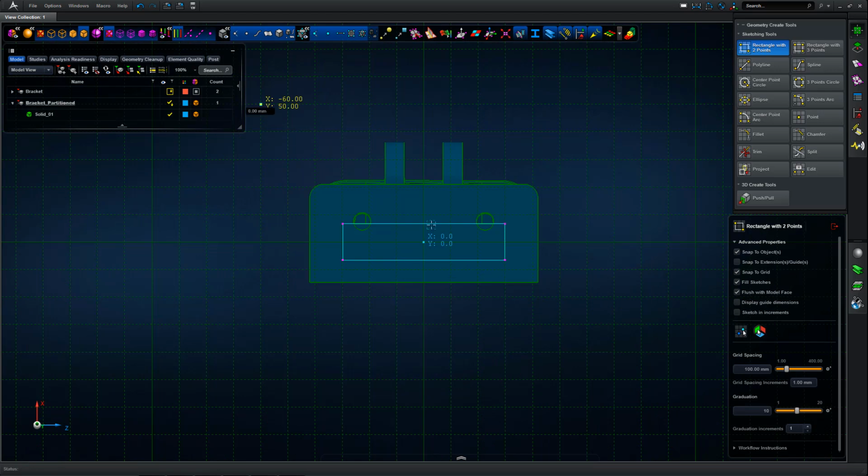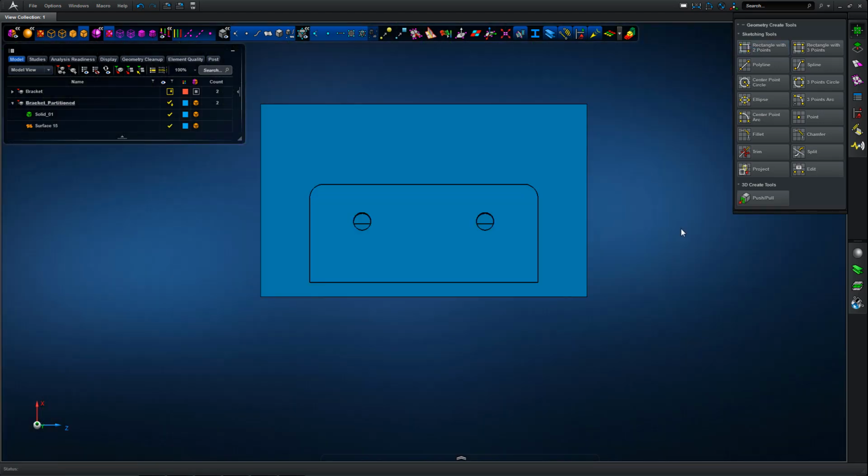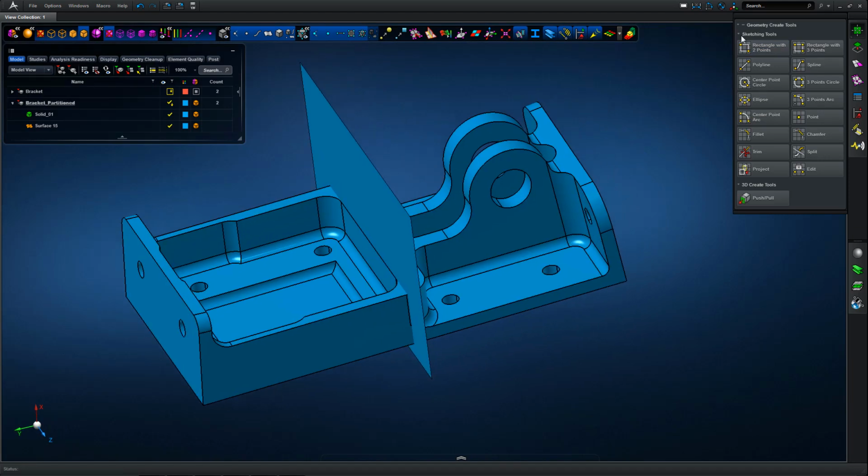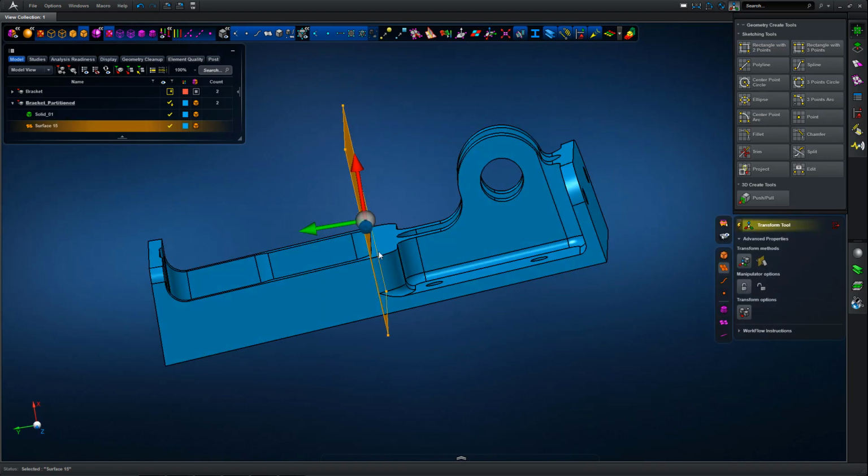So we're now going to look at a different technique called partitioning, which allows us to break up a solid into different partitions or regions which we can mesh separately. First of all, we're going to define some cut plane geometry or cut surface geometry using the sketcher tools and some simple transformations in Apex.